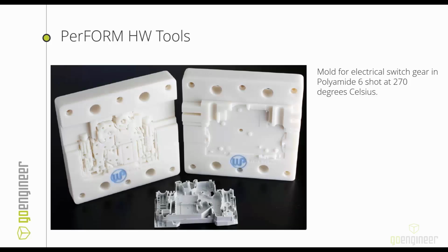PEEK material would also work well for running this, depending on, again, what you're shooting into it. With that, I don't think we have any PEEK materials, at least validated on the Origin machine. But if there were photopolymer versions of that which third party companies are making, you can get them and get it dialed in on your own. And then you have your own specific secret sauce you're working with there if you want.